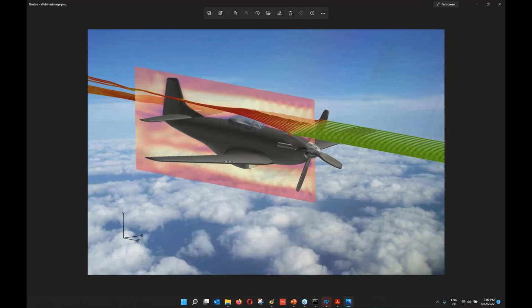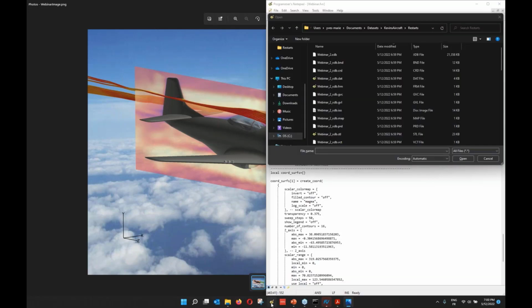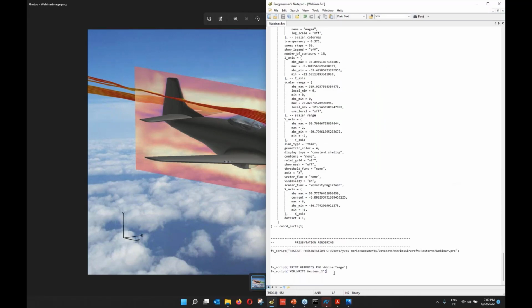Well, in batch. It was not headless batch, but we created it interactively. And FieldView can be run in full batch in just the same way without the interface coming up, with just a command line option. So all of that is fully documented. But here you go. This is really the initial stages for learning to do scripting. We recommend that you do your work interactively, save a session FVX, and then use those simple scripting commands for performing operations.